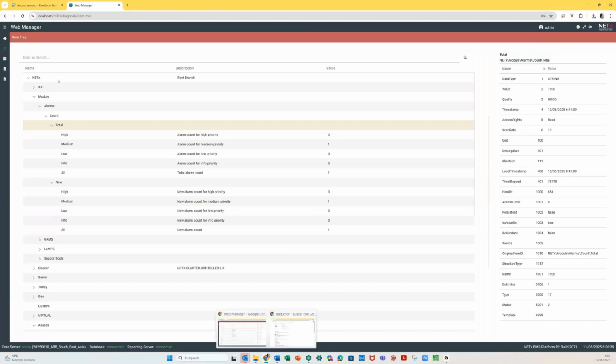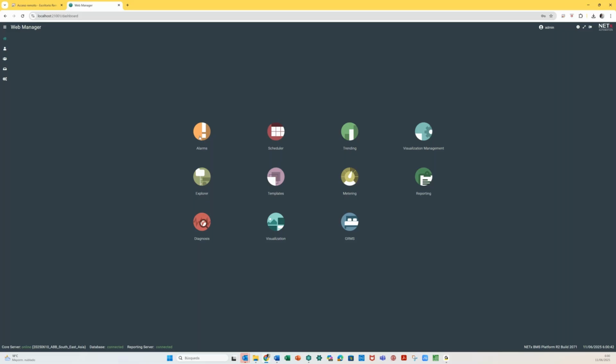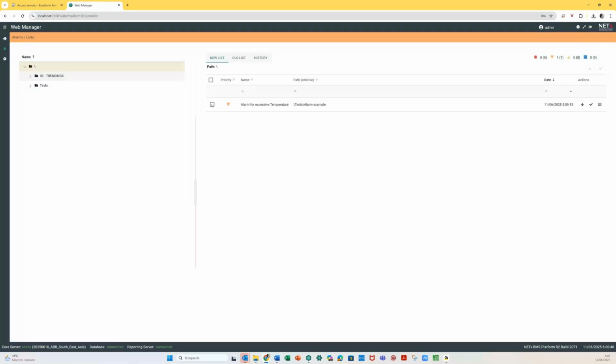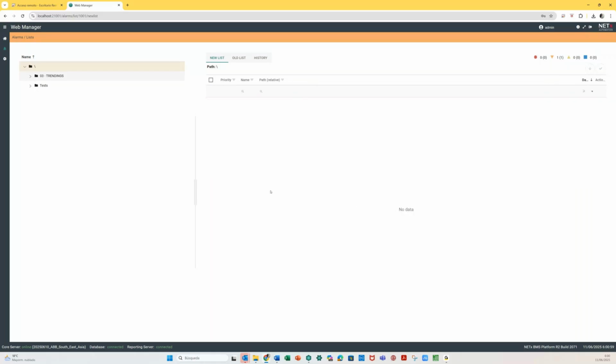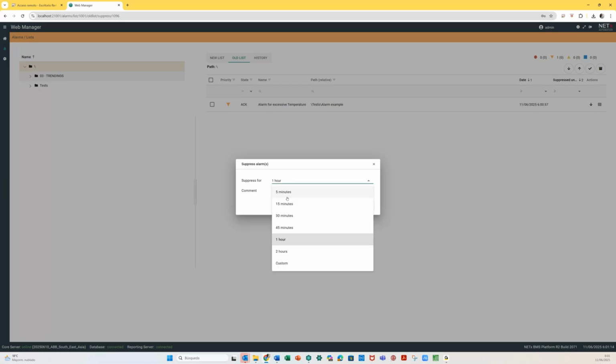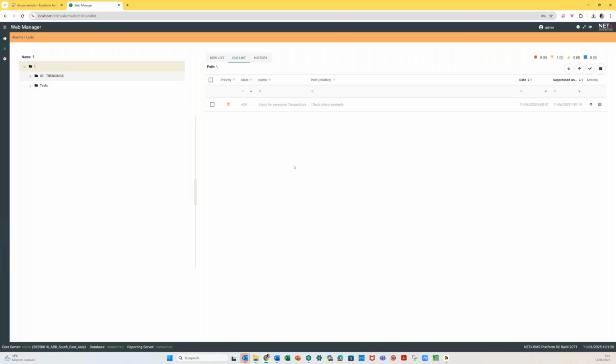If I go here again to my alarm and I say, okay, let me acknowledge or block, suppress. Let me acknowledge it, comment, okay. If I acknowledge it, it's not in the new list, but it's in the old list of alarms because it's still active. Okay, I can suppress the alarm also. I will ignore it. So you can suppress the alarm for 1 hour, for example, or 2 hours, custom or whatever. You can suppress it, so it's not an alarm now, but everything is in the history.